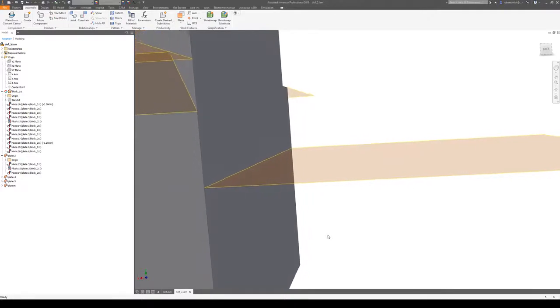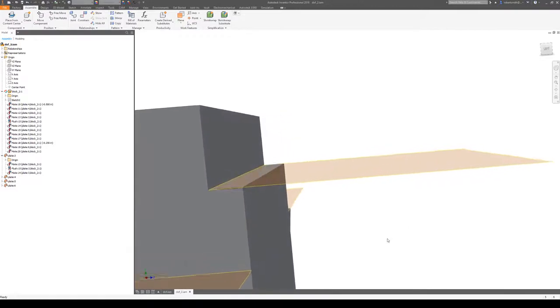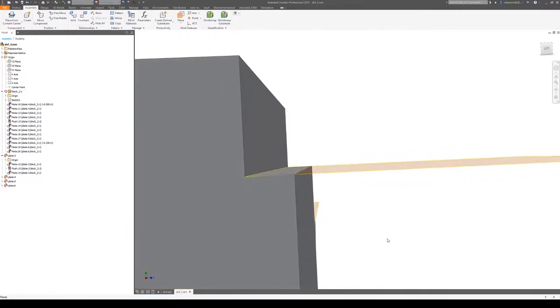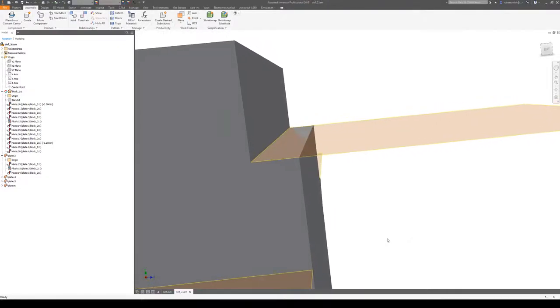So what do you do? Well, I've seen a few techniques employed. One is to just put a step in there. Obviously this one's exaggerated, but just even a little step, enough to get more than one row of nodes where those two things meet. You are modifying the design simply for analytical purposes. It's not something that's physically there in the model.